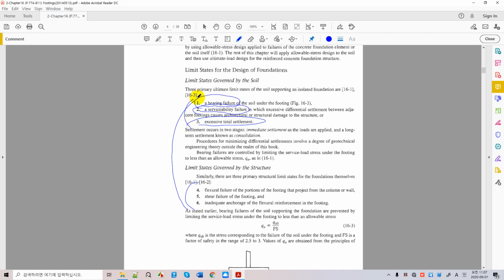And the 3 related with soil conditions, right? And the other 3 probably related with the concrete structure. First of all, flexural failure should be avoided when vertical loading is acting on the structures. Also, shear failure must be avoided strictly. And the last thing is that